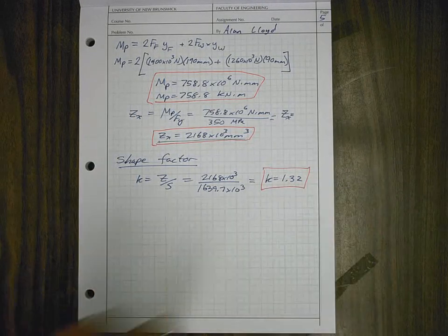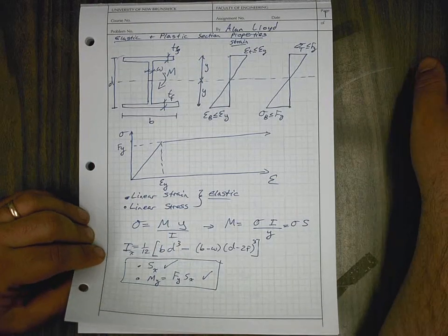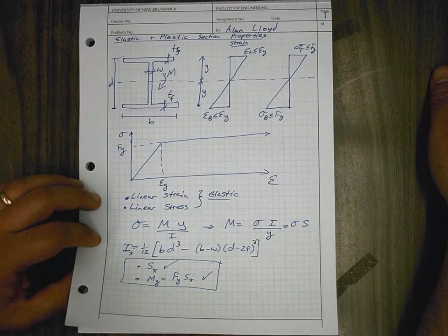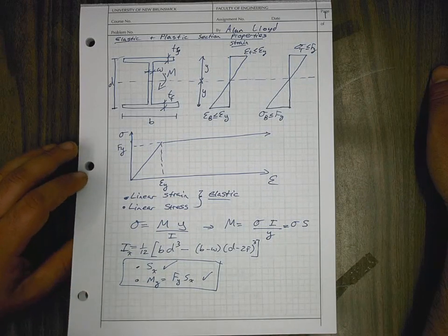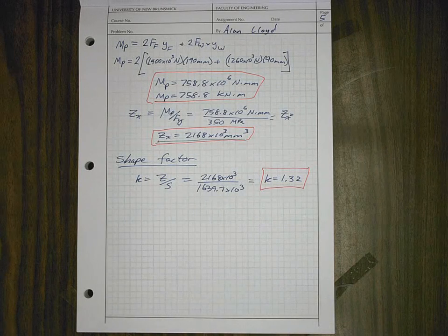So this is interesting. Interesting to note that when we get rid of a lot of the material that separates an I-beam or W shape from a rectangular shape, the area inside of the flanges, that doesn't change the shape factor all that much. We recall that a rectangular one had a shape factor of 1.5. So this is part of the reason why we use these W sections, or pretty much the predominant reason, is that they are tremendously efficient in terms of their area, which corresponds to their mass and corresponds to their cost, and also the load on the structure, as that's very efficient, a low area and a very high moment resistance, and also the high plastic moment resistance as well. So we don't see a tremendous loss in plastic capacity. And that's what makes these W sections or I-beams so efficient.